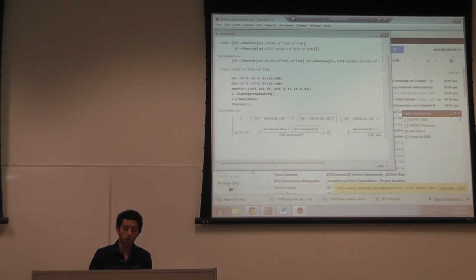my S11, contour plot. S11 on the beam, x1 goes from 0 to 1.5, let's say. x2 goes from negative 0.25 to 0.25, the length of the beam and the height of the beam. Contour labels true. I want to see the numbers. Plot label S11 in MPa.